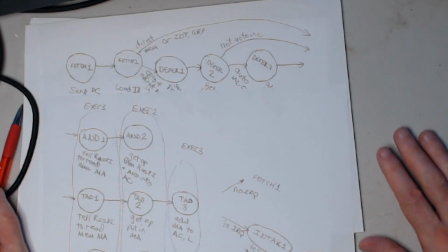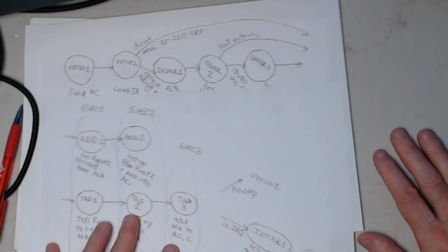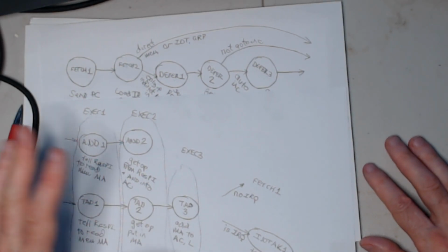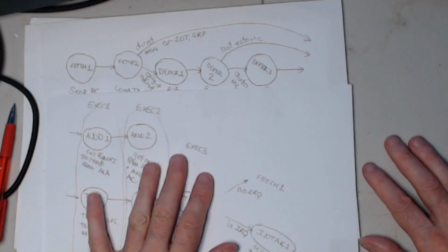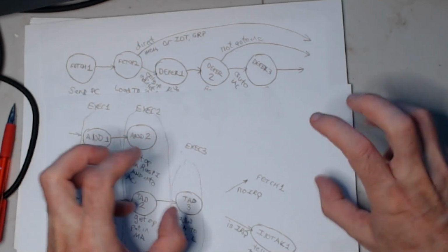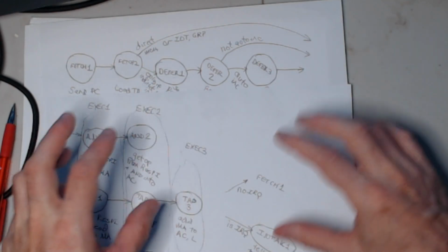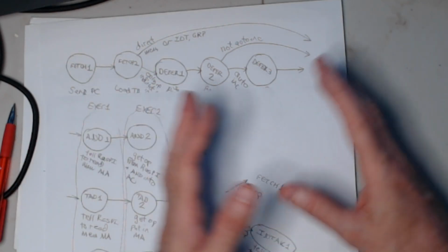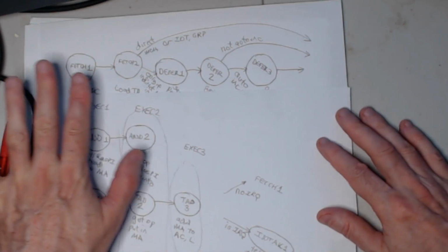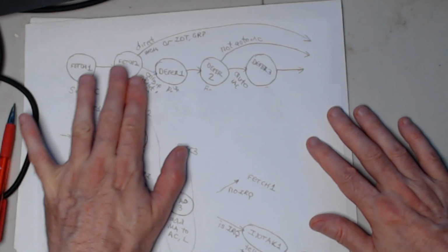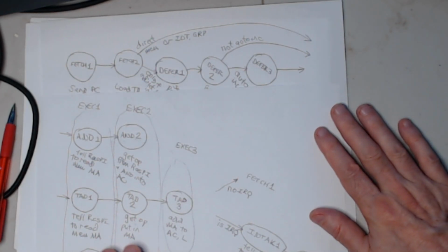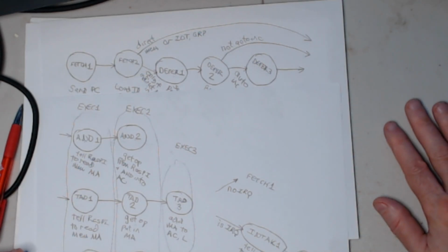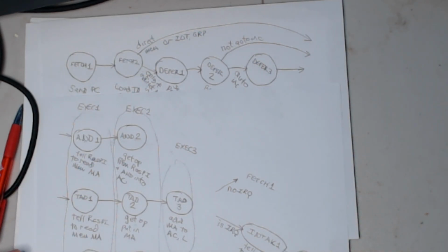So there's the state machine, and the state machine tells it what it should be doing each cycle. It reconfigures the gating between all the other registers, depending on what state it's in and what's in the instruction register, are the big things. So there's that. Again, hope that was entertaining for you.